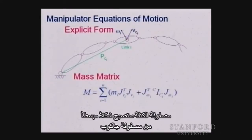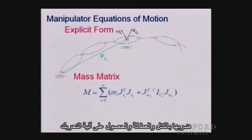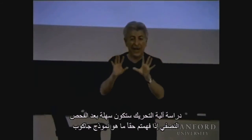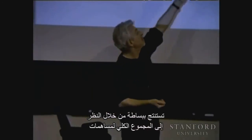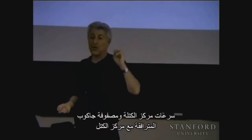So the mass matrix will become a very simple form of the Jacobian. That's why I'm going to insist on your understanding of the Jacobian. Once you understand the Jacobian, you can scale the Jacobian with the masses and the inertias and get your dynamics. So going to dynamics is going to be very simple if after the midterm you really understood what the Jacobian is. The mass matrix associated with the dynamics of the system comes simply by looking at the sum of the contributions of the center of mass velocities and the Jacobian associated with those centers of mass.